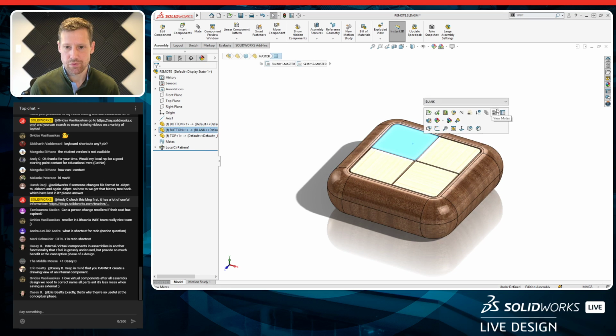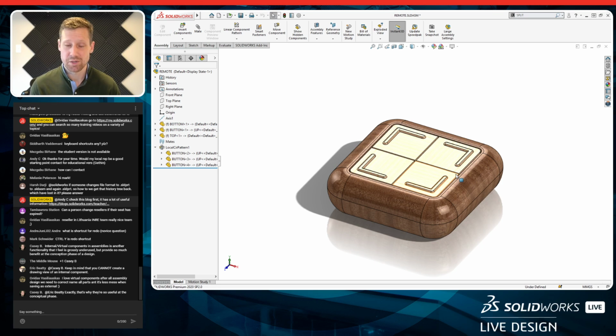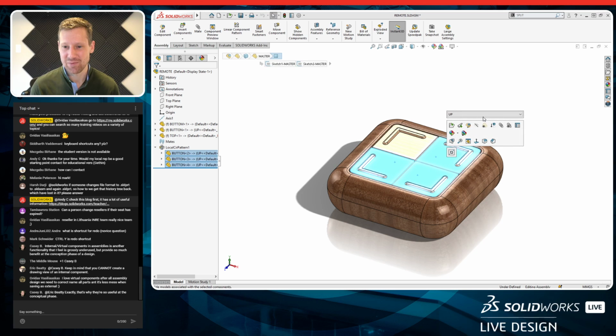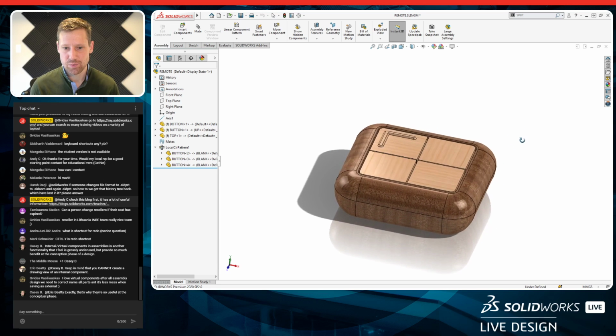Okay, let's change our configuration here. Let's say this one's going to be the up button. I just select that part, use this drop down, I can choose that configuration and hit check. Of course, because I was the seed, it's going to propagate that to the other ones. I didn't actually want that to do that, but that's okay. I'll use a control select and then I can change all these back to what I want. So, all right, that looks pretty good, I think.